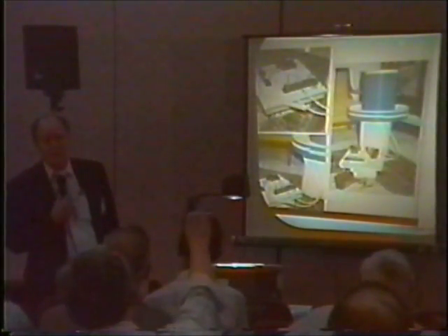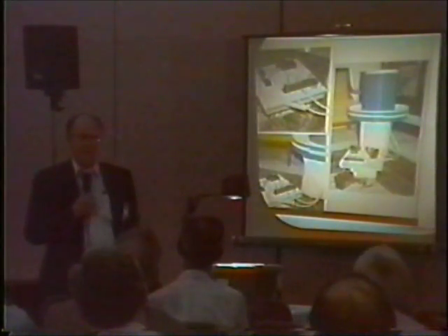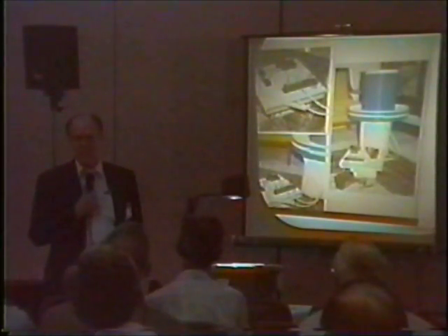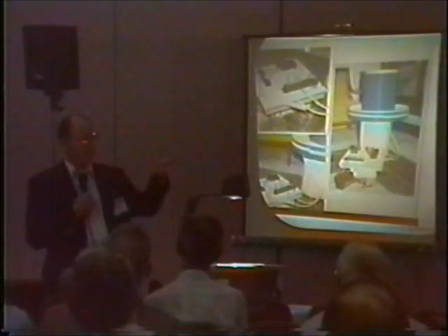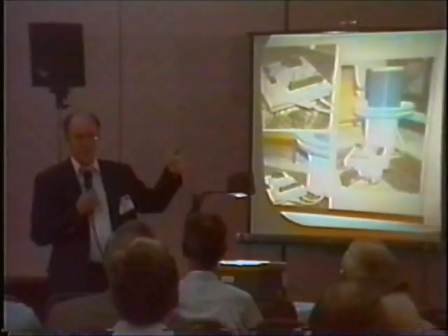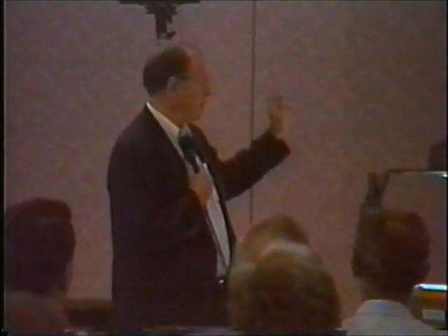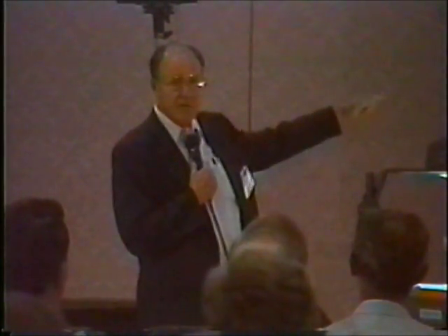Yes? What kind of wire are you using out there? Well, what you have to watch out for is the voltage difference between 2 wires. So if there's 750 volts different protection on one wire there, between the 2 wires you would have 1500 volts possibility that you could play with, so that you could have a differential of voltage going as you go up of 1500 volts, and you'd probably want to stay at about 1000, which would give you a 500 volt safety factor.